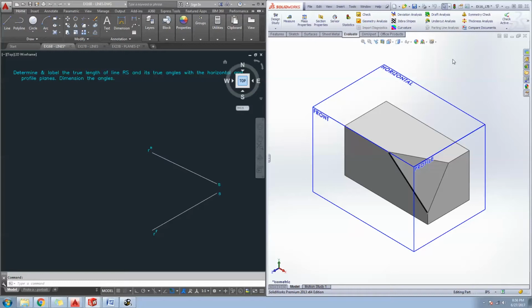The thing about descriptive geometry is that the computer is constantly trying to lie to you about lengths or angles, and it is so easy to get fooled. For this reason, we're going to put the letters TL next to a line that is in true length. As an example of the deceptive nature of lines that move in and out of true length, let's go back to looking at that black line.